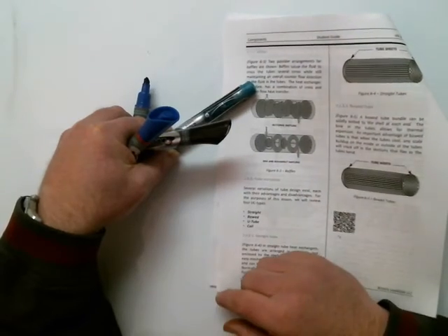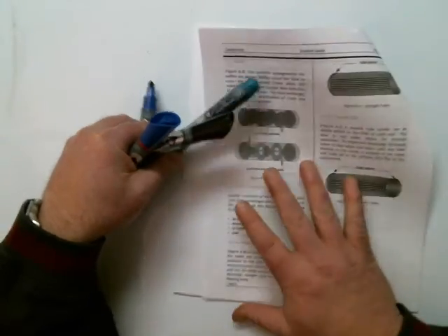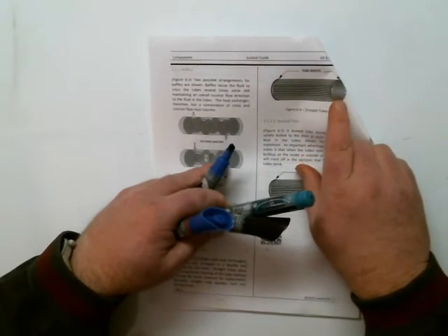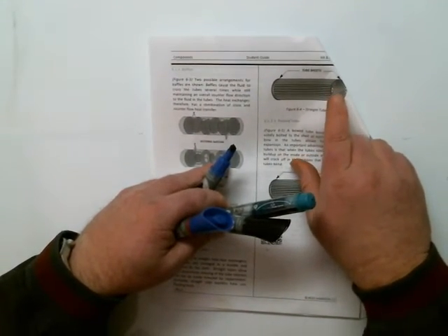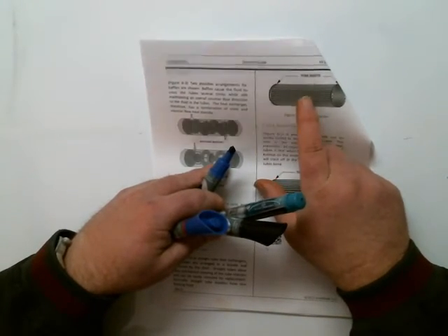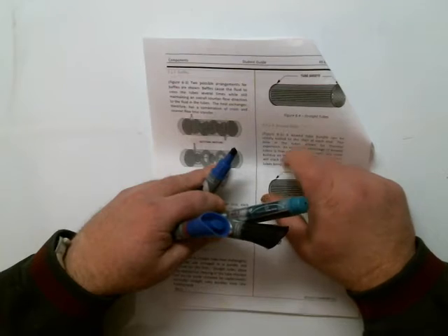All right, next thing we talk about is the tubes in here. We have a couple variations of tubes. The tubes could be straight. They could just go straight through. And this is a good example. You can see the end of the tube sheet here where there's the penetration and the fluid can go all the way through. A good advantage of straight tubes is they're easily cleaned.